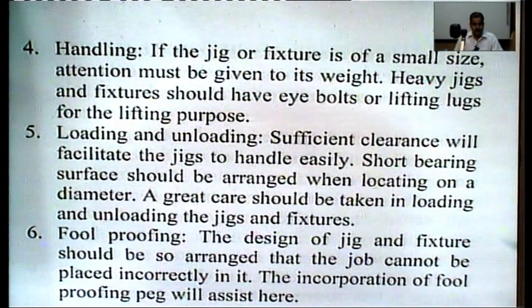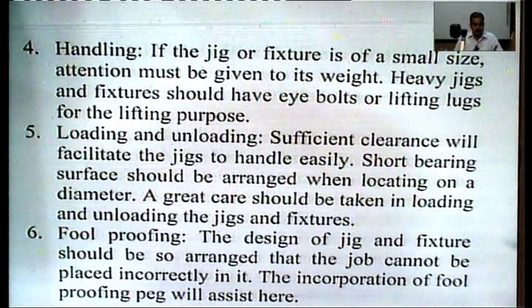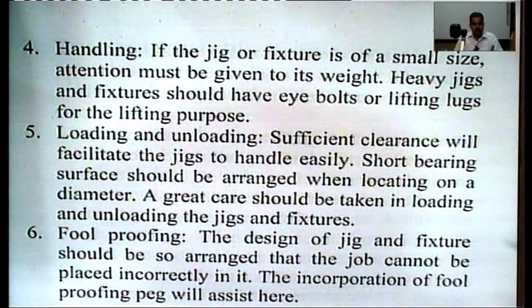And for carrying jigs or fixtures which are heavy in nature, from one place to another, some eye bolts or lifting lugs should be there for their transportation.